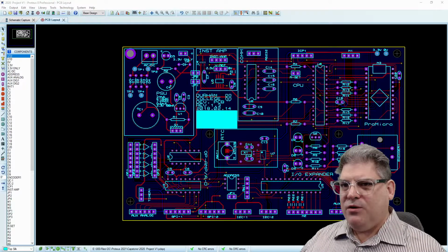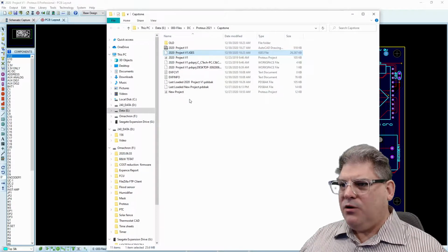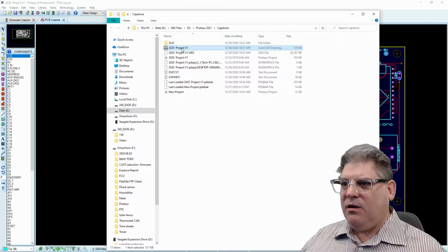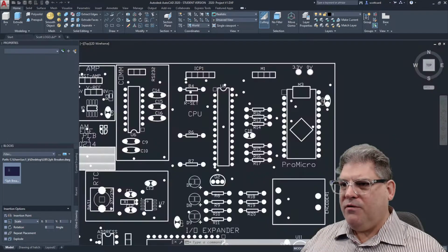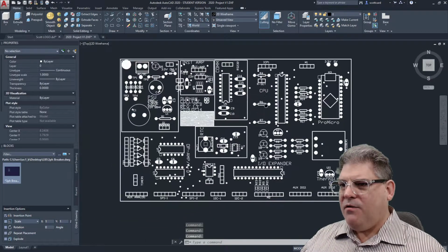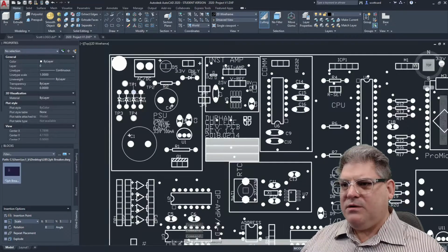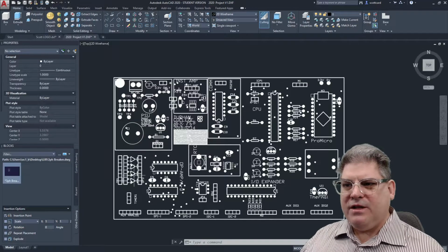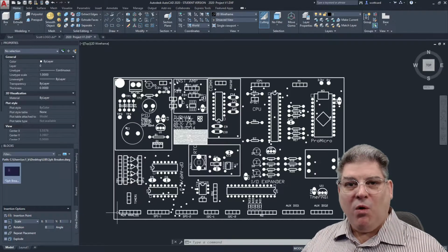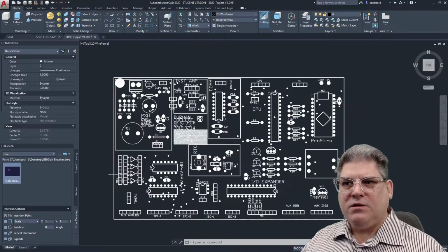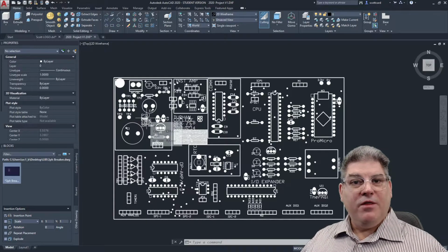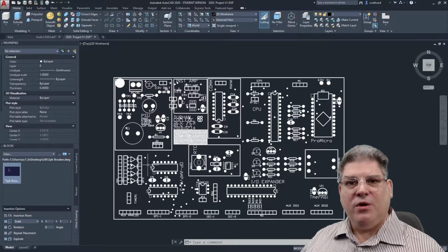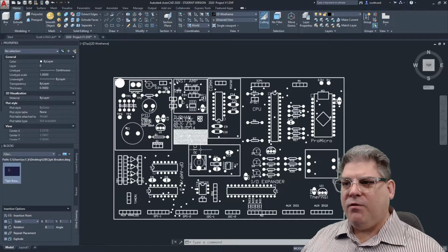And now if we go back to that file, there should be a DXF file there, which, sure enough, we have. And we have something reasonable. I mean, it's not perfect, but it at least shows our board edge and shows us where most of our components are. You'll notice the one thing that's missing is something that we would probably want, which is the holes. So perhaps we want to keep the top copper because that's going to show the holes, and go from there.